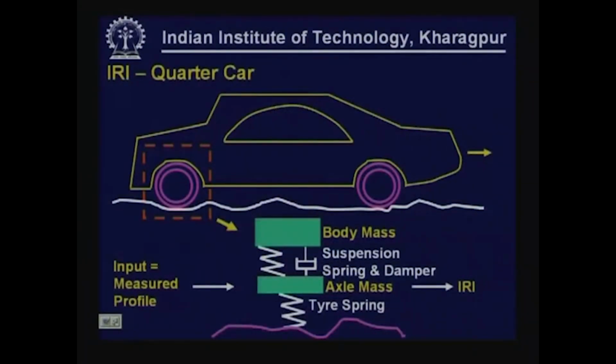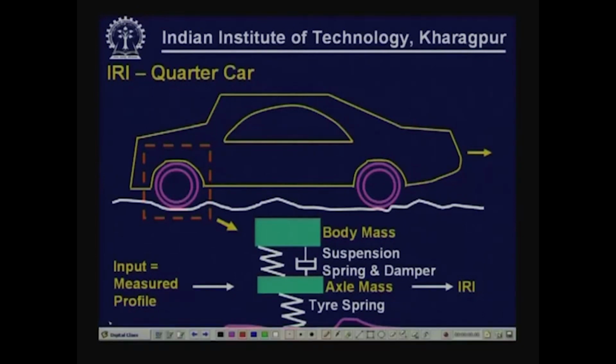This is the quarter car that we are referring to. So, we consider just only 1/4 of this vehicle given by one wheel system. So, here we have the wheel and also the part of the load that is coming and various suspension systems. So, this can be represented by this mechanical model.